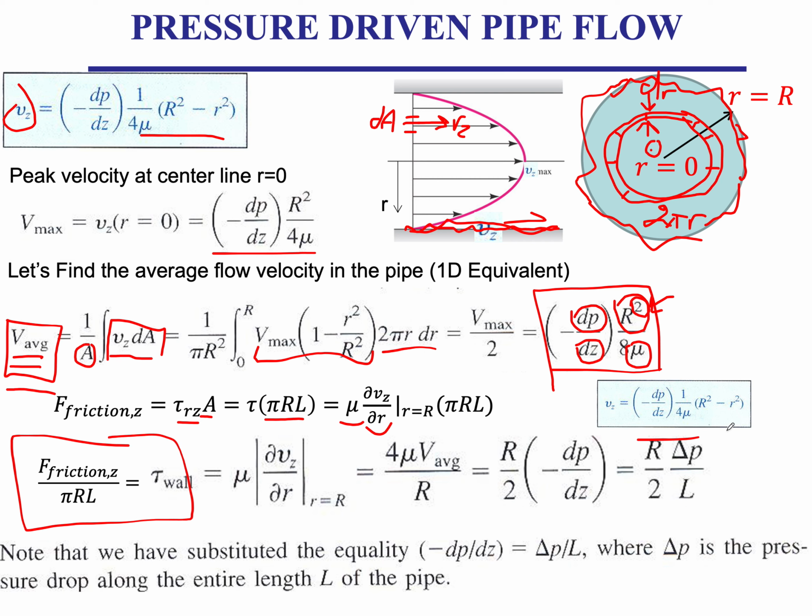and you get a relationship between your friction and the pressure distribution. Let me stop here for a second, and we will discuss this in a little bit more detail, the friction as a function of pressure drop. So on one side we have friction, and on the other side you have the pressure difference across the pipe. So we see there is some equalization of frictional forces, or frictional shear, with the pressure forces between the inlet and the outlet of the pipe.